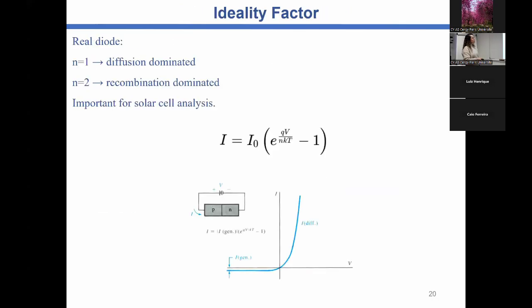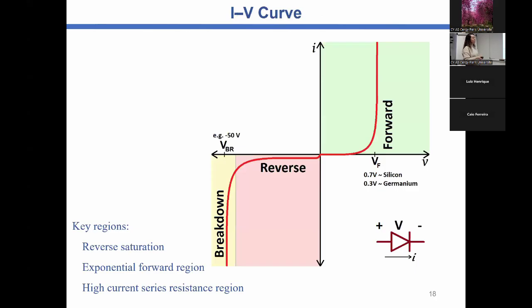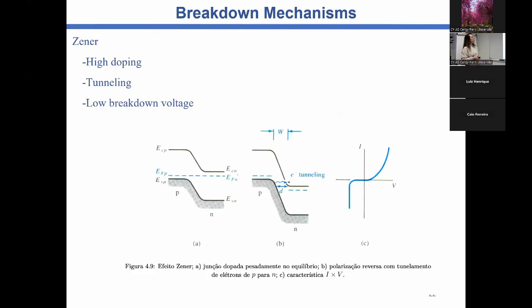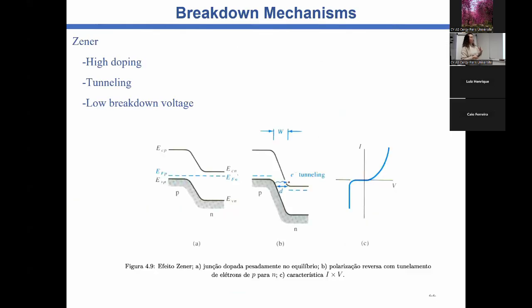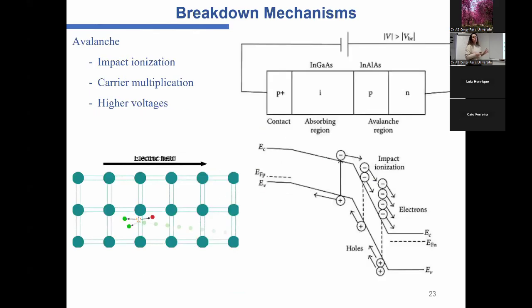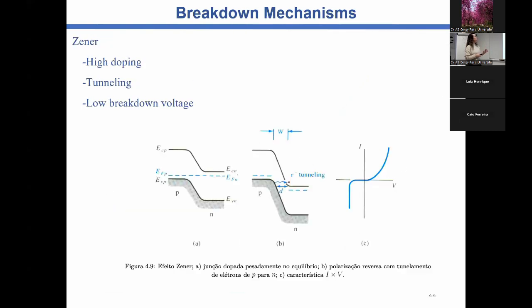Yeah, we saw in these IV curves that in terms of a reverse bias, we have this breakdown in the transport. That means at a certain reverse potential, we could have transport even though it should be blocking. And this transport can be ruled by two kinds of breakdown. We call them Zener breakdown and also avalanche breakdown.